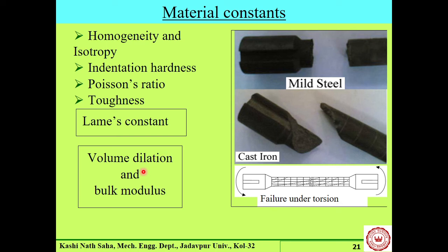And then from our stress analysis we had an idea of hydrostatic pressure, uniform stress you can say, and their relationship, that hydrostatic stress and our volumetric strain. Okay. So P by delta. We represented hydrostatic stress by P and this volumetric strain by E. So that P by E gives the bulk modulus. Yes. Okay. So this is what we get from the measurement.